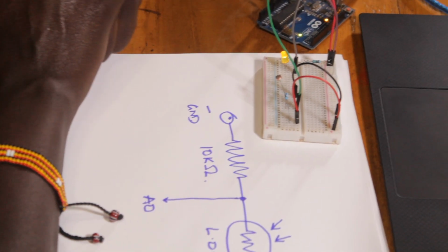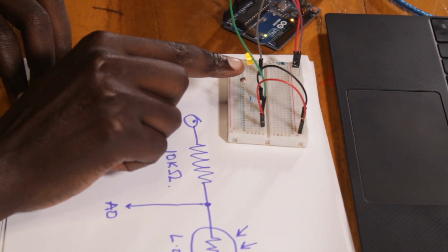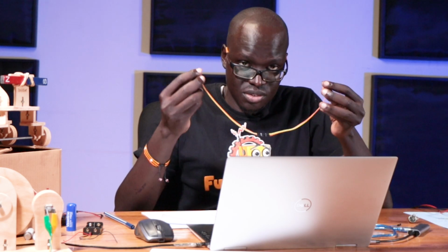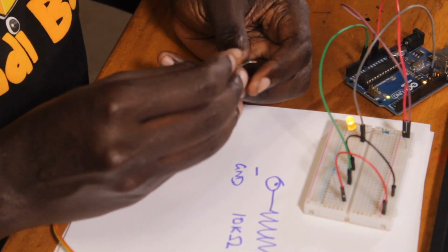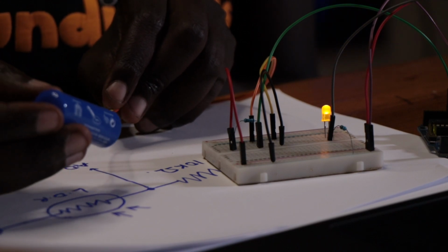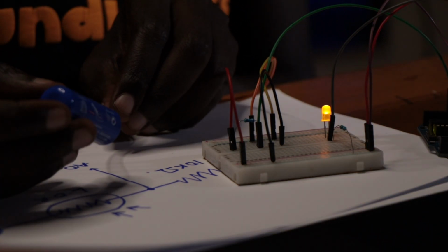All right, so we have our code that's working. If it's all working well, then the brightness of the LED should be dependent on how much light the LDR is receiving. In order to make this a little more visible, I created a really long cable so that we are able to see this clearly without it being a distraction. It's just a jumper wire that's been extended. What we're going to do is get the LDR, stick it here. And the goal is that you should be able to see, as I cover it there, the LED goes brighter, right?